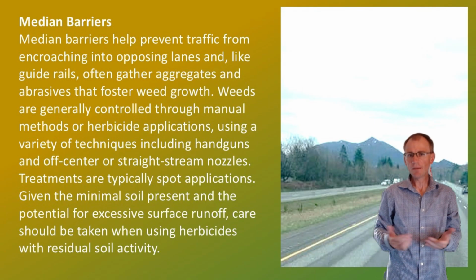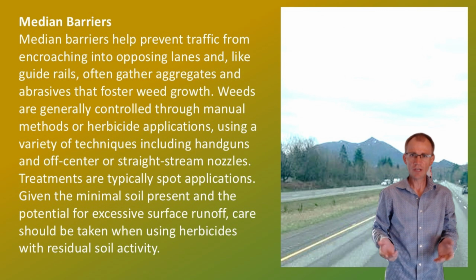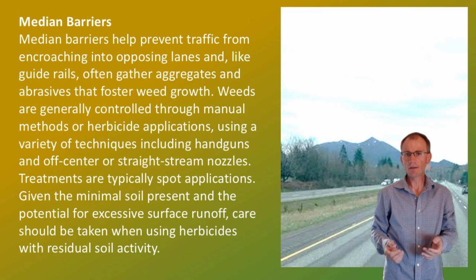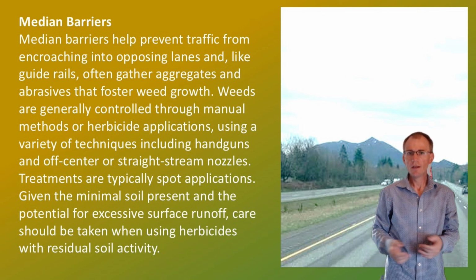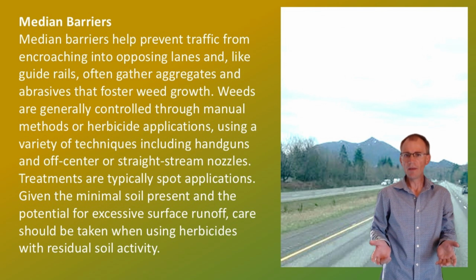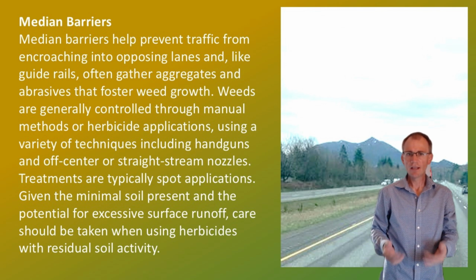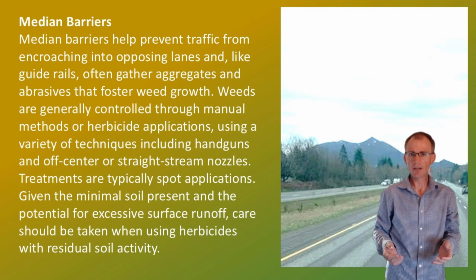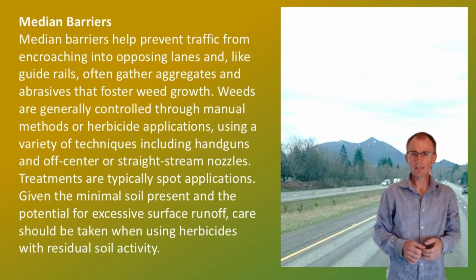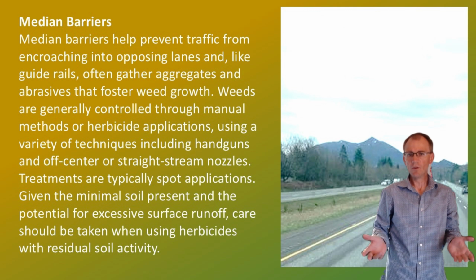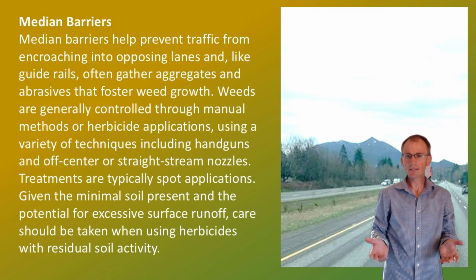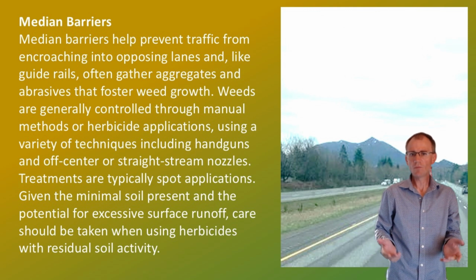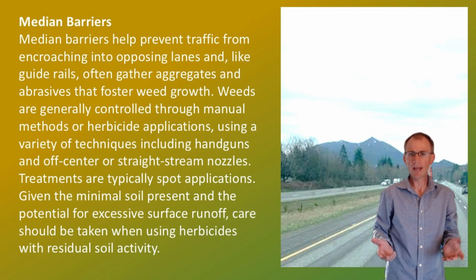Median barriers. Median barriers help prevent traffic from encroaching into opposing lanes and, like guide rails, often gather aggregates and abrasives that foster weed growth. Weeds are generally controlled through manual methods or herbicide applications using a variety of techniques, including handguns and off-center or straight stream nozzles. Treatments are typically spot applications. Given the minimal soil present and the potential for excessive surface runoff, care should be taken when using herbicides with residual soil activity.